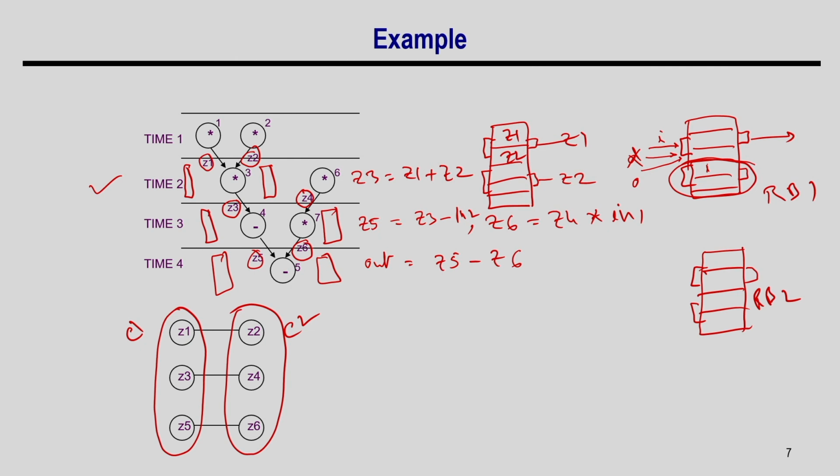There is a series of registers, so you can just put them in some places. But what is stopping me here is that Z1 and Z3 were mapped to the same register because their lifetimes were non overlapping. But here, since I have already decided that Z1 and Z2 go to this register bank, I cannot put Z3 here, because then I have to access 3 values, right.